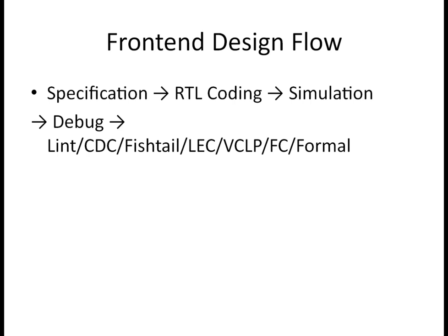So let us discuss single bit synchronizer. As I said, the first synchronizer is your two flop synchronizer, where we are using two D flip flops back to back. In the two D flip flops back to back, when data is transferred from one domain to another, if your data is changing in the setup or hold window of the flop,